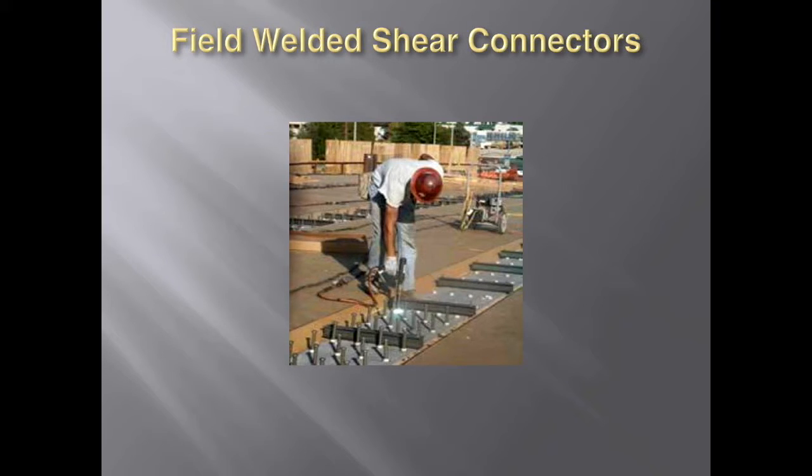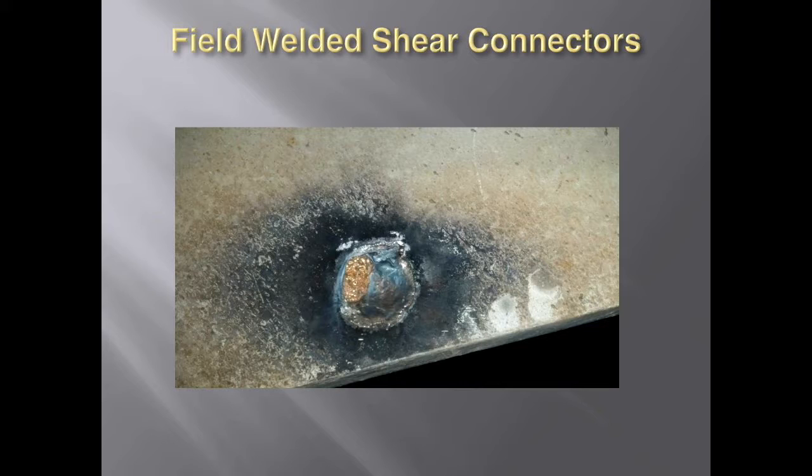So we'll go through and check all of them. Walk through with a hammer, usually an 8-pound sledgehammer, and sound each one. A good welded stud will have a ring to it. One that's not welded will have kind of a thud to it. So if anybody wants to check studs, they're more than welcome to come out and try it with us. Get your arms worked out.